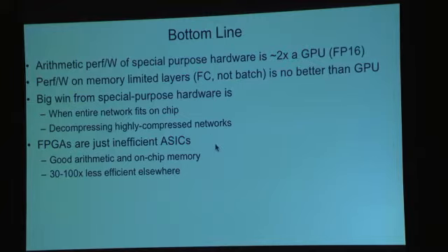FPGAs are just inefficient ASICs. They're great at arithmetic and memory. They're really bad when you've got to build things out of the LUTs, which also includes things like decompressing the networks and doing other than the standard arithmetic operations that come built in.